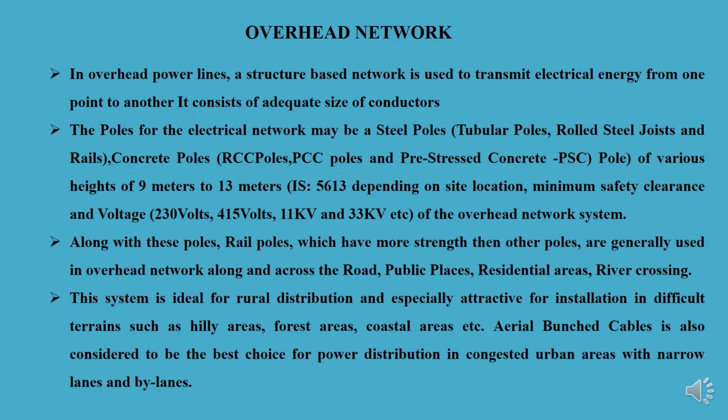Site location matters: if the bearing capacity of the soil is not good, if it is a water logging area, or if hard rock is not available for the particular foundations, then according to that you have to decide whether it is a steel pole, a concrete pole, or a pre-stressed concrete pole. So it depends upon location, minimum safety clearance, and voltage. Now voltage may be 230 volts, 415 volts, 11 kV or 33 kV of the overhead